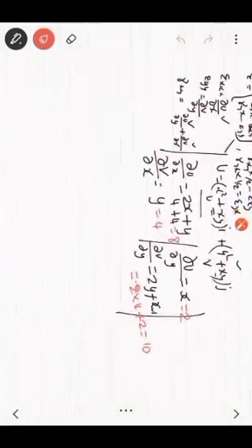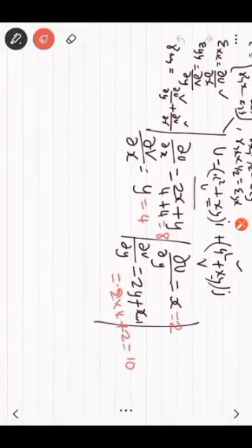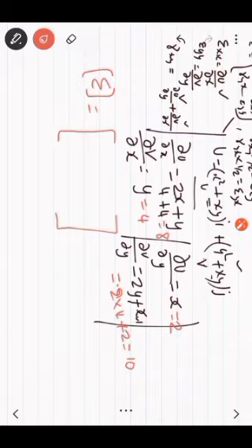You know that. So substitute that, you will have this value. Now write down the strain tensor. This is gamma, so you have to divide it by 2, then only you have the strain tensor correctly. So what is dou u by dou x? That is 8. What is epsilon yy? That is dou v by dou y. Dou v by dou y is 10. What is this one?